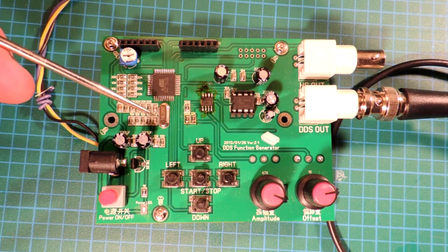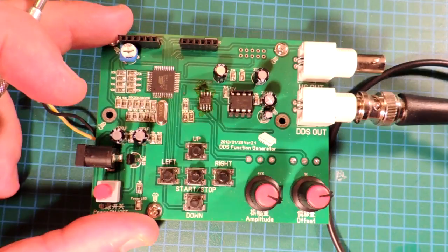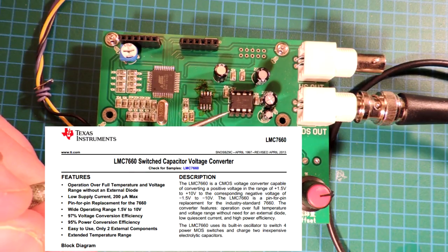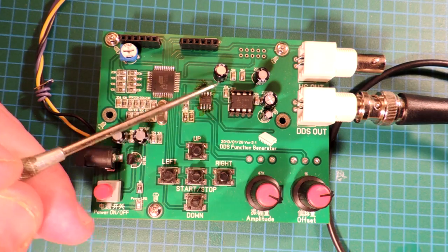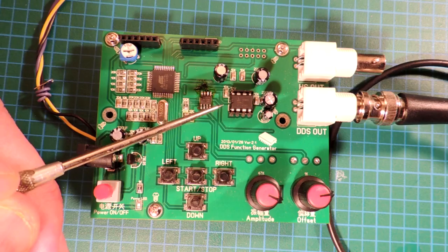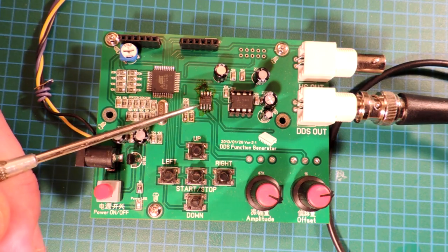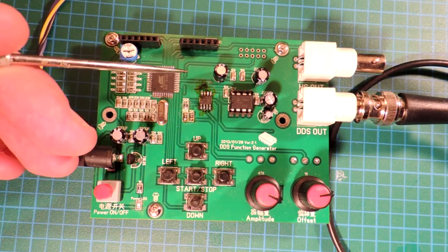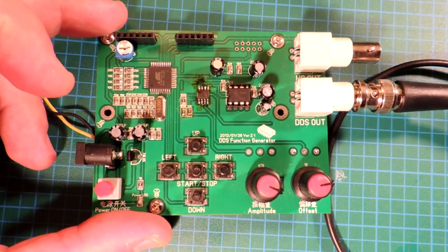Crystal, of course, associated with the processor. Pop up the data sheet here. It's socketed. I have no idea why, but it's a voltage inverter, a capacitive voltage inverter. It runs fairly slow, and yes, there are no real great provisions to keep the noise off of that from being coupled into the system. A dual op amp here. You can see it's been soldered twice. That's basically because I blew up the original one.